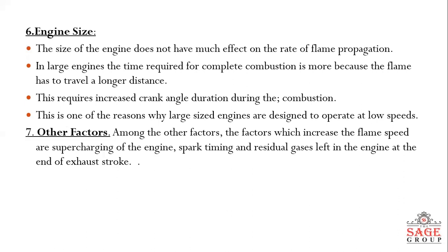Some other factors that affect flame speed are supercharging of engine, spark timing, or residual gases that are left in engine at the end of exhaust stroke. If we supercharge the engine, the intake pressure will be increased, and during the compression stroke, we can achieve a high pressure and temperature. So it will reduce our initial preparation phase and also speed up the second phase of combustion.